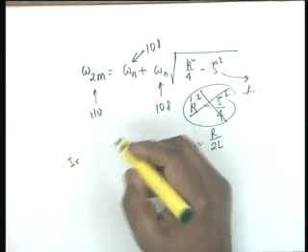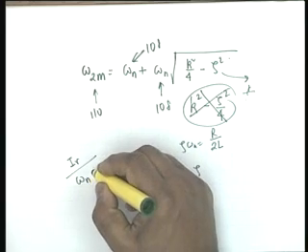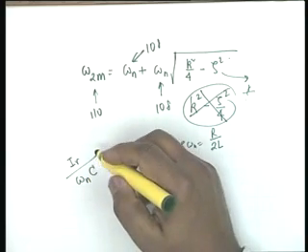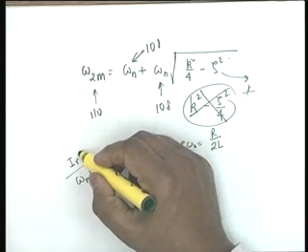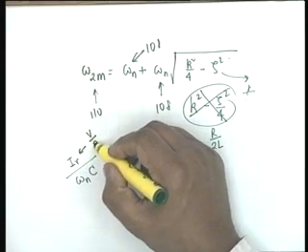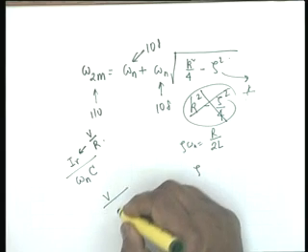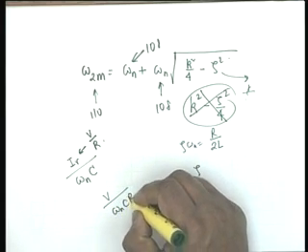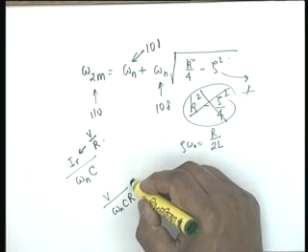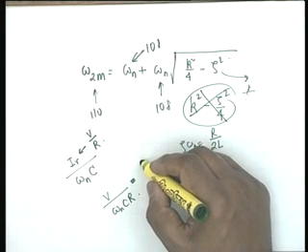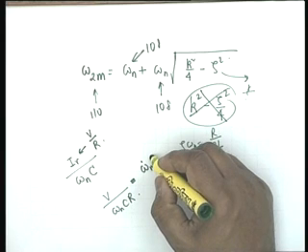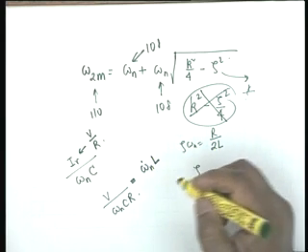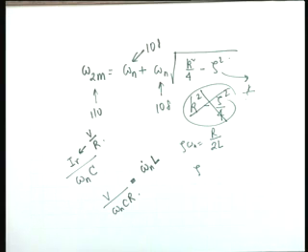You see, at current resonance, the voltage across the capacitor would be I resonance divided by omega n times C, and I resonance is V by R, and therefore this is V by omega n C R, which is equal to omega n times L, no, there is no R. Have I made a mistake?